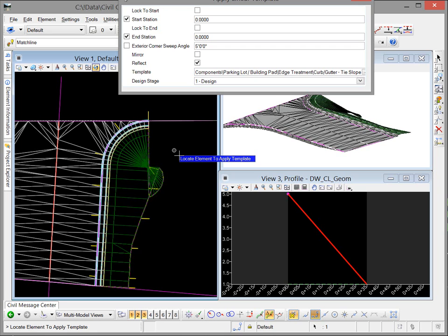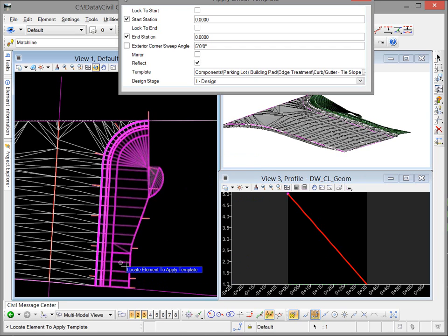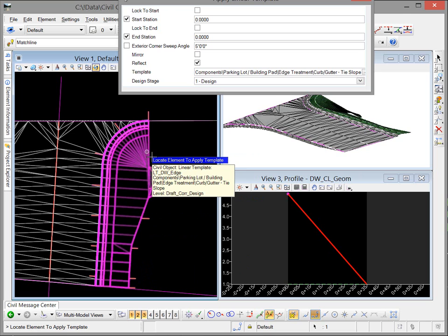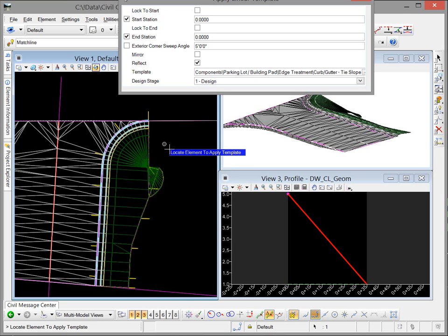You can simply go draw a graphical line in your plan view, and if it sees that line added as a corridor reference, then instead of doing traditional fill slopes or cut slopes, it'll just go to that line and stop. And so that's a good way to eliminate things like these bow tie examples.